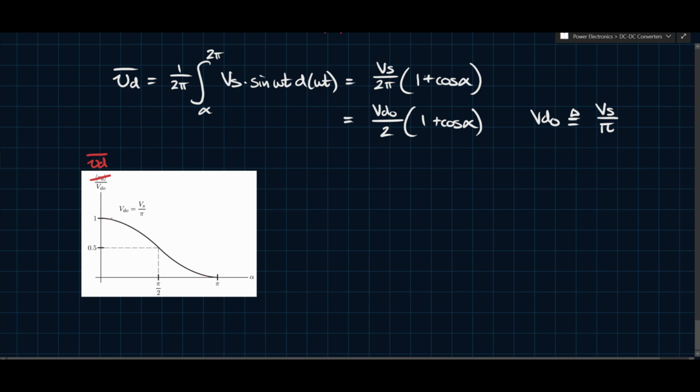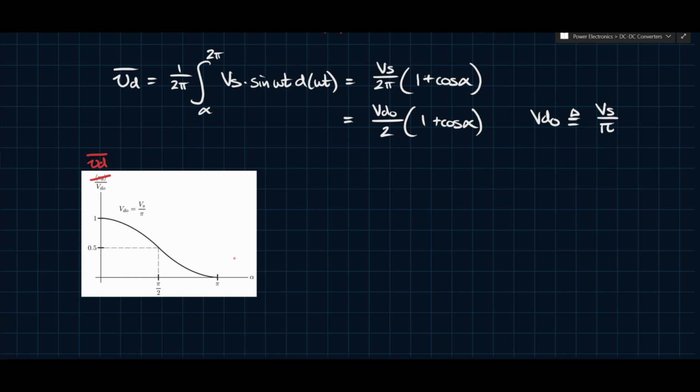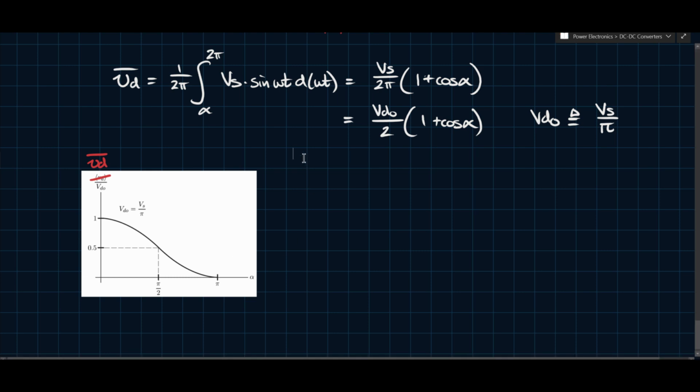So you have a sort of handle. You can control the output average, whereas in the diode case you couldn't. So this gives you obviously another degree of freedom. Now you can implement some type of closed loop control. You can change the firing angle according to whatever the requirements are of your circuit, and you can implement more and more interesting and elaborate circuits, is really what it comes down to. More useful, practical circuits.